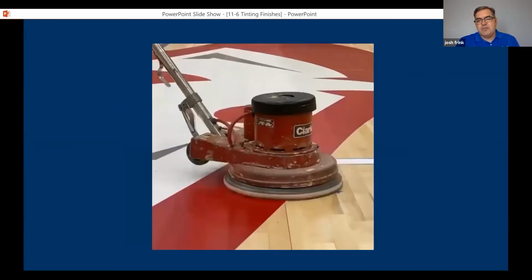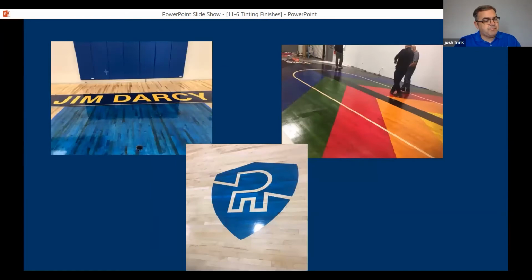And then you can screen it, which I don't know if you've ever put a screen on paint on a gym floor before. It is scary, because if that paint is not completely dry, you move that red line several feet and it becomes pink, and then you're getting the sanders back out. But with this product being suspended in our finish, 2 hours later, we're getting a buffer on there, screening it, abrading it, applying another coat. It is so much easier to do now.